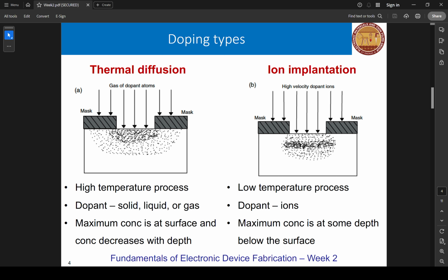For p-type dopants, they can penetrate deeper into the wafer. Why, sir? Because they lost less energy traveling through SiO2. And why n-types? I just got confused. Your n-type dopants are losing more energy. Your p-type dopants are losing less energy because they are smaller. You are talking about p-type dopant boron? Yes, certainly, boron is a group three element. Boron is much smaller than even phosphorus or arsenic. Arsenic is much bigger.